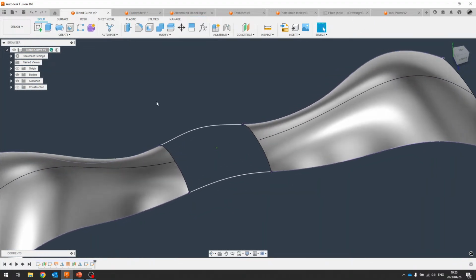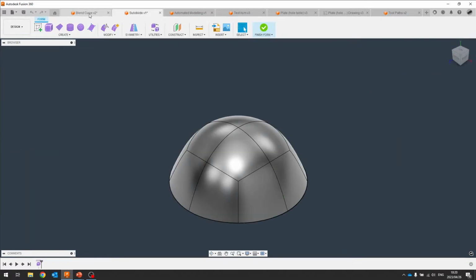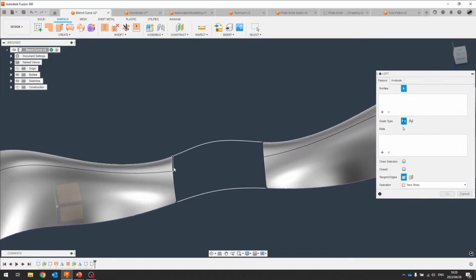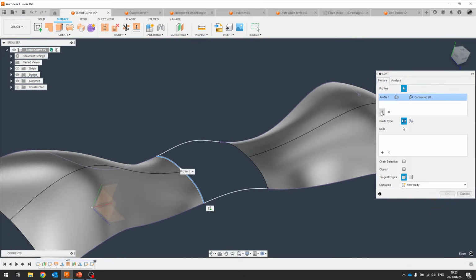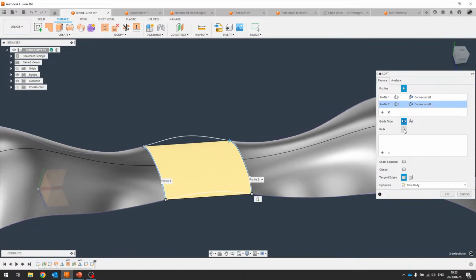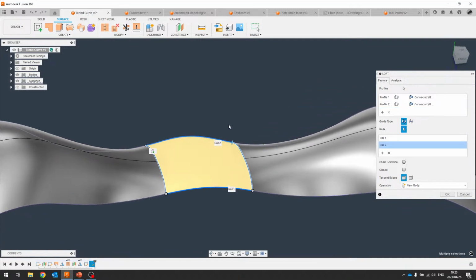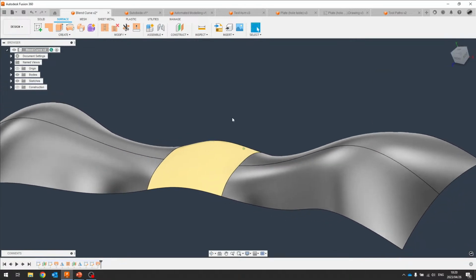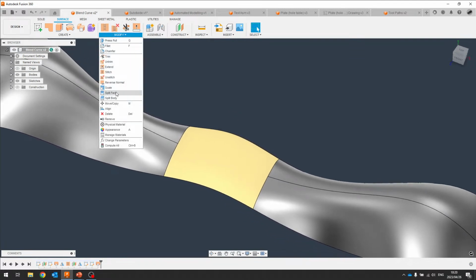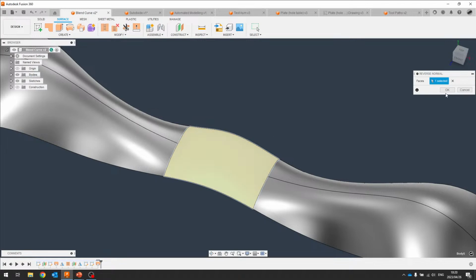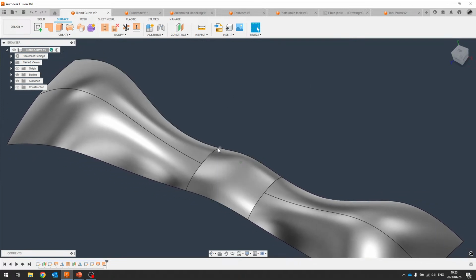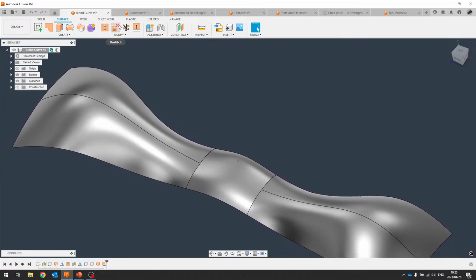We could continue on now. If we finish sketch, we'd be able to do something like, it's got a surface, we could do a loft from one side of the component across to the other. So just our standard loft practice here, and we can then add rails and use those curves as rails for that loft. So a nice quick way to bridge a gap, create a surface across that gap. Let's just go ahead here and reverse the normal on this face and get that nice continuous surface. Okay, so that's your blend curve option.